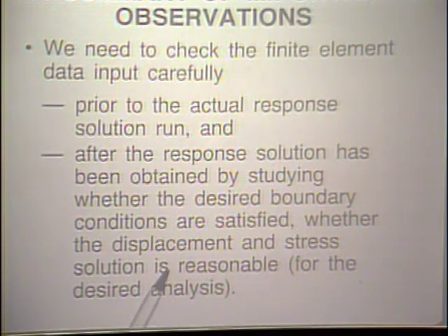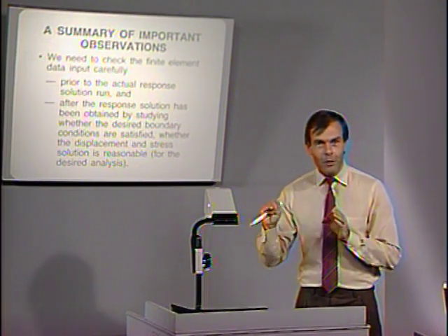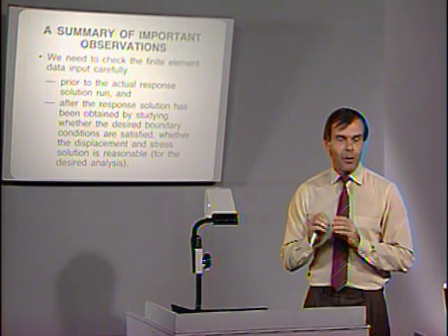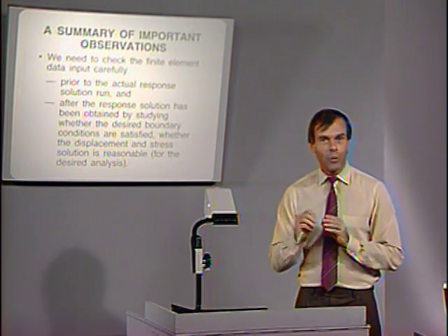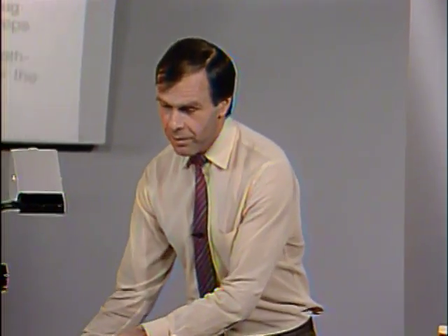Of course, the same holds for the stress solution. You remember that we looked at the stress plots for the mesh that was fixed at the bottom, and we could directly see there were errors there. In other words, the error of having fixed the boundary at the bottom of the plate. So this step is most important, and we have seen an example in the analysis that we just completed.